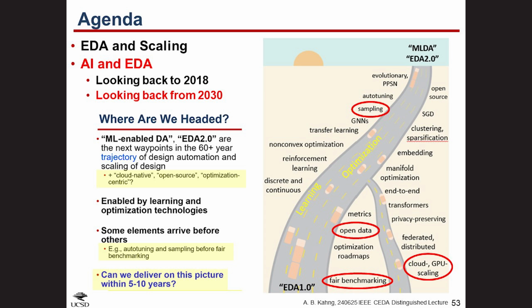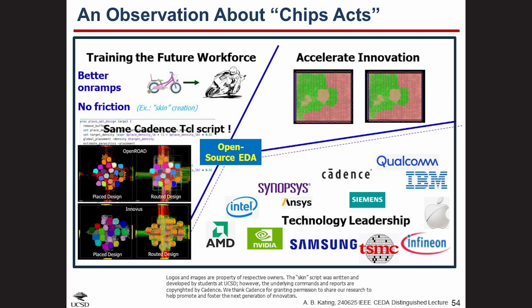So all the metrics other than runtime are normalized to protect Foundry and IP providers' intellectual property, and WNS and TNS are normalized to clock period. But the bottom line is that the new placer dominates the other two placers. It places the more than 800K instances in 32 seconds. And so you would ask, can architects or RTL engineers use this kind of thing?